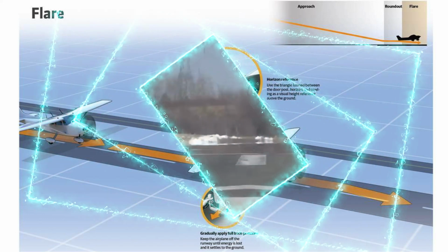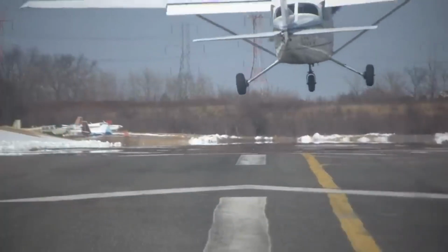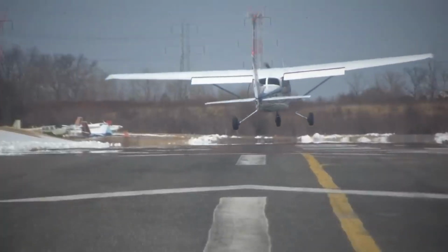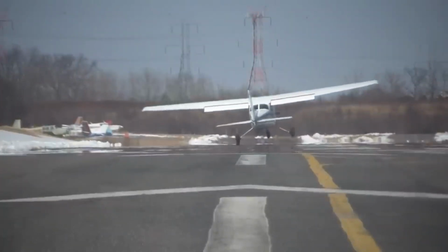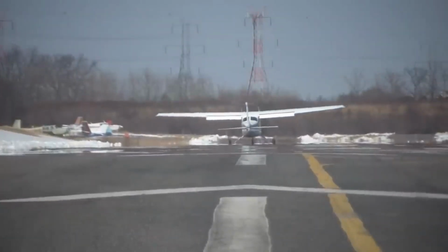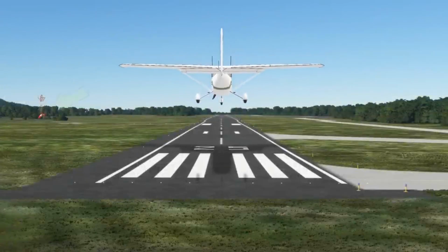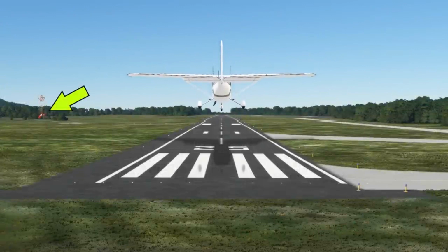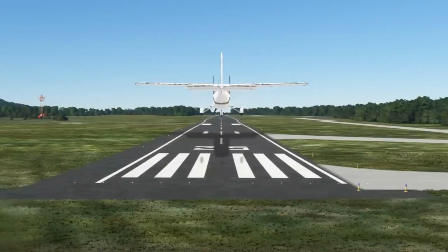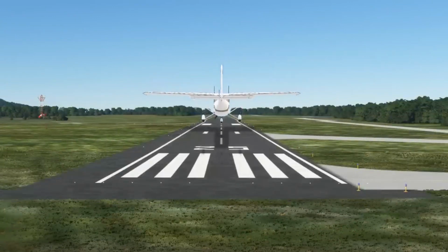Crosswind touchdown. If the crab method of drift correction is used throughout the final approach and roundout, the crab needs to be removed the instant before touchdown by applying rudder to align the airplane's longitudinal axis with its direction of movement. If the wing low method is used, the crosswind correction is maintained throughout the roundout, and the initial touchdown occurs on the upwind main wheel.